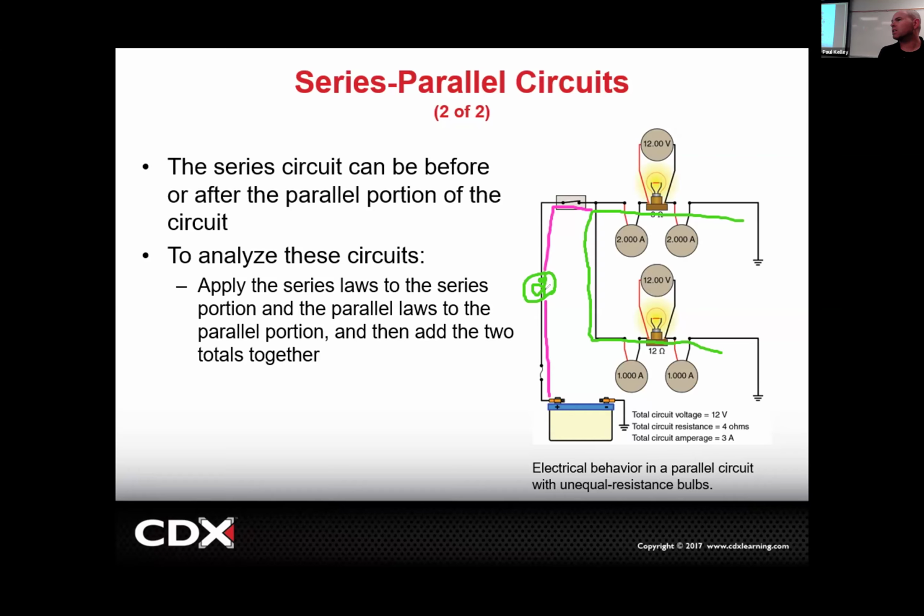So I'm going to give you some really nice clean numbers. Let's go with 6 ohms on the series part. And then let's just say we had a combined 6 ohms of everything over here. Everything this way was all 6 ohms combined. That would mean that you'd drop 6 volts right here, and then these would all drop the remaining 6 volts. So it's a little bit weird to think about, but you would understand it using Ohm's law.